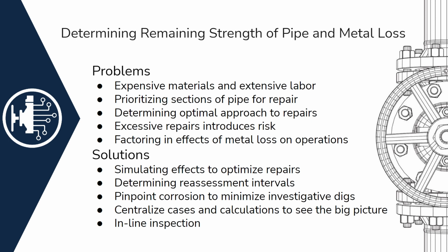And obviously, if you went to do a corrosion investigation here with all these issues, and remember, girth welds are a big deal, you could see the poor workmanship. You could see many defects of gaps and porosity, and oh my gosh, there are so many defects here.